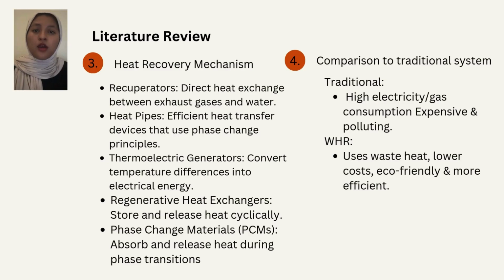and it will enhance the efficiency by converting wasted energy into useful heat. For the heat recovery mechanism, basically the core mechanism of a waste heat recovery water heater system involves transferring heat from a waste stream, such as exhaust gases, hot fluids, or steam, into a working fluid, which is typically water, using a heat exchanger. Common heat recovery methods include recuperator, heat pipes, thermoelectric generators, regenerative heat exchanger, and also phase change material.